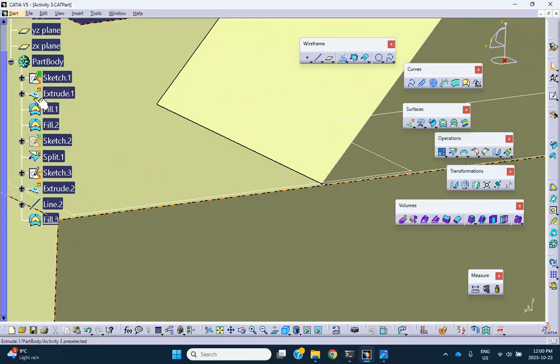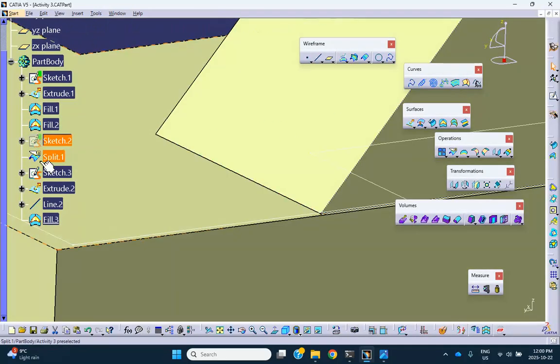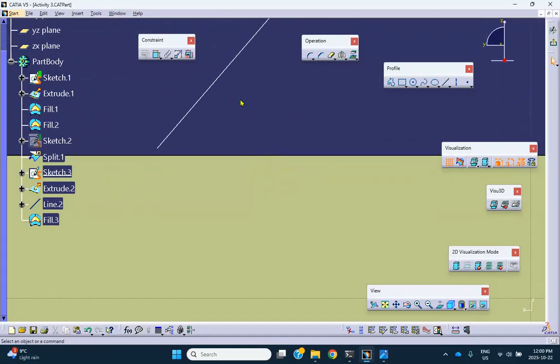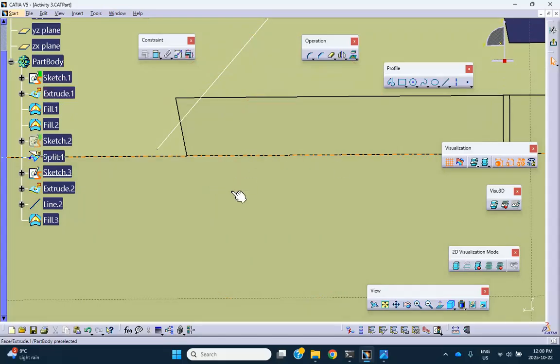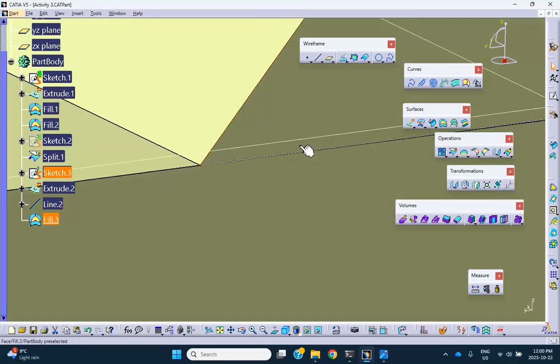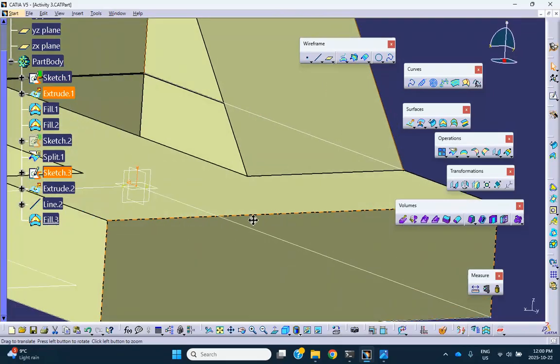I believe this trapezoid was, was it this sketch? No, maybe that sketch. Yeah, right here. You see this? That's what the problem was. So I can fix it. So I select this point, control that point, and you make it coincident. Okay, very good. Nothing changes. Everything else is going to stay put. Now we go to the other side and try to FILL it.